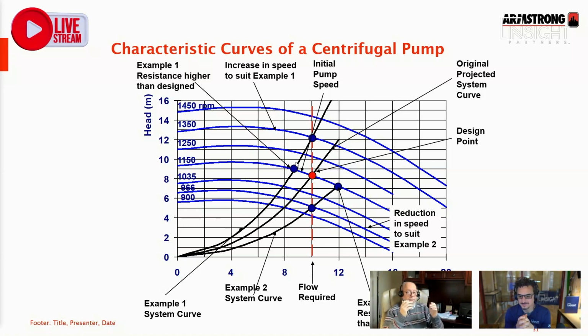Yeah, that'll get you there. Yes. So understand that when you go out and look at a job and you take your readings across your pump and you're trying to figure out what is going on in your system, and you're seeing head losses that are higher than what you designed it for, and you're pretty confident in your design, get out of the mechanical room, stick your head above the ceiling, and look. You would be surprised at what you will find looking at the system.